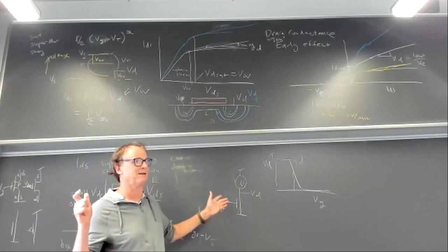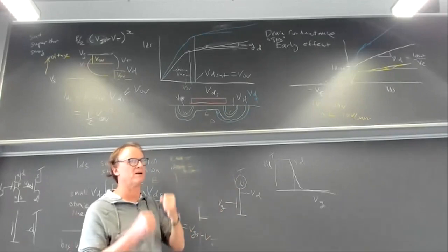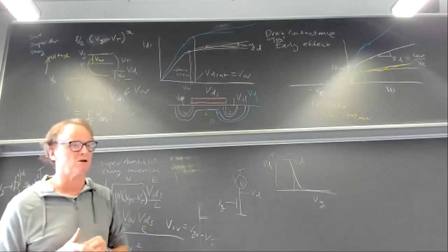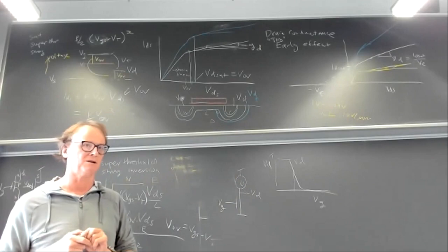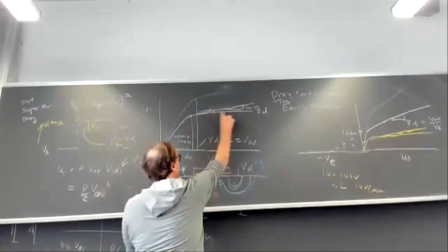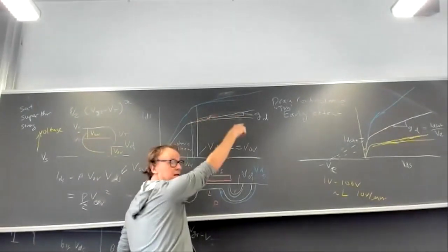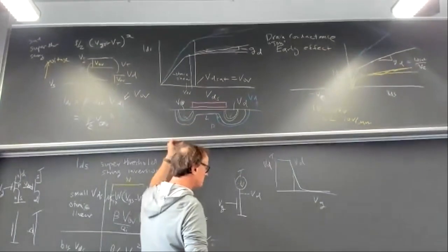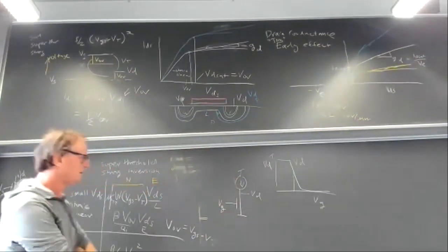Every amplifier is like that. Two current sources are fighting it out for the output voltage. And what do I mean by current source? It means the current doesn't change with the voltage very much. It's a stiff current source like this. Here, the current doesn't change much with voltage. Okay? That's how you make an output voltage amplifier, by fighting two of those against each other.